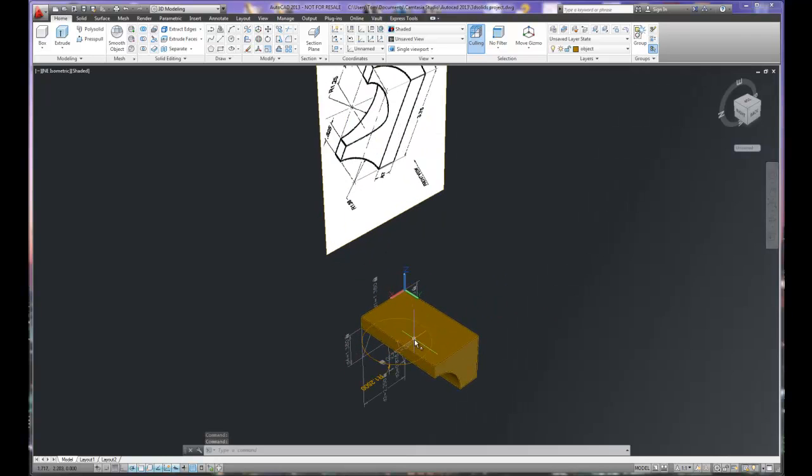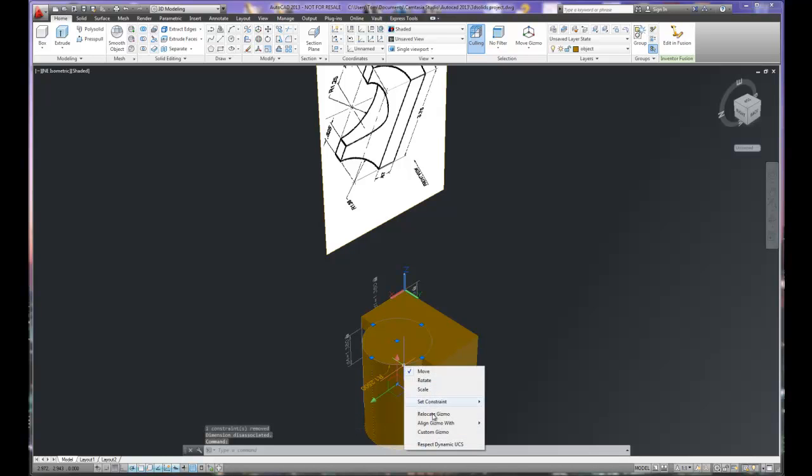So now what's going to happen is I have to cut this object or make this object into a cylinder. And so we're going to extrude this. I could also use the press pull, but I can extrude this. So we're going to extrude this. And it's going to ask us to extrude, and I can just pick and drag the direction that I want to extrude. So I'm going to extrude this direction. Now I could change the color of this. I can pick it, right mouse click,